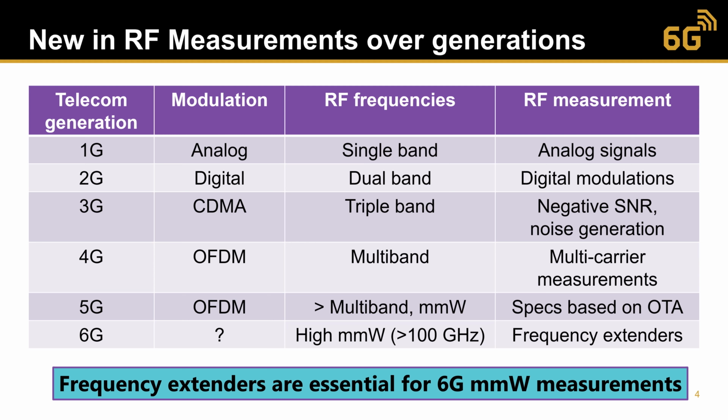The 5G systems continued on a similar path as 4G, and added the new feature of 5G millimeter wave networks. Those networks can be deployed starting from 24 GHz up to 71 GHz. The 5G millimeter wave systems require antenna arrays to be implemented at both ends of the radio link. The number of antenna elements in such arrays can be hundreds, and a high number of conducted measurement interfaces is not practical or physically feasible.